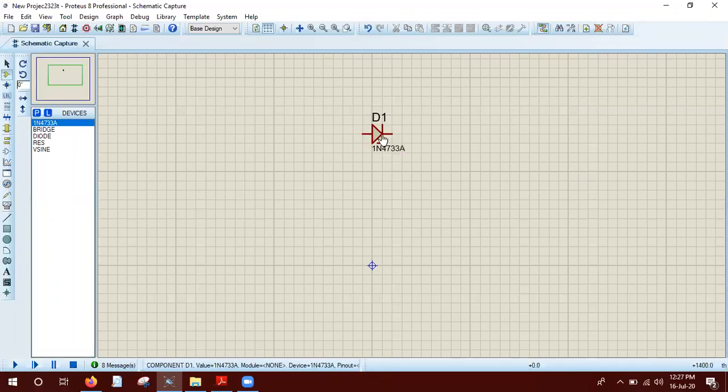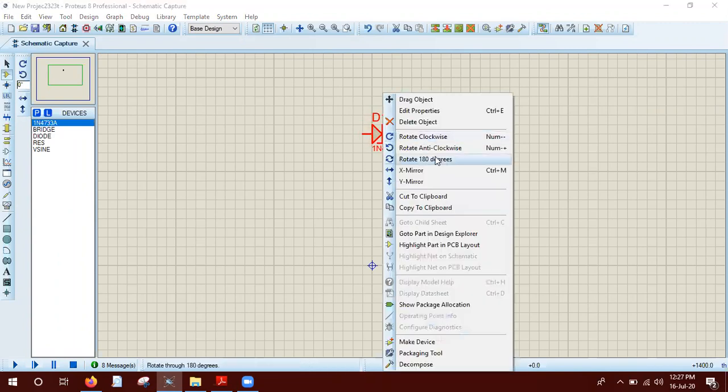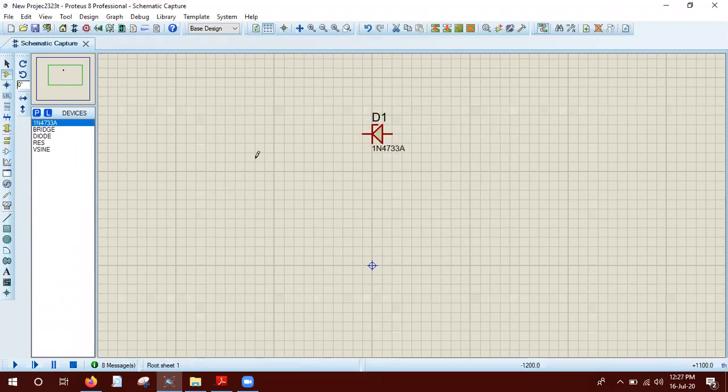We all know that the Zener diodes will operate in the reverse bias situation. So let's rotate it 180 degrees and apply a DC voltage. So we go to the generator mode. We apply a DC voltage, and let's see what the Zener diode curve is. And finally, we need a resistance probably. Yeah, we need a resistance to show the output.